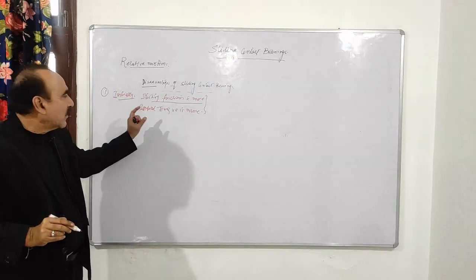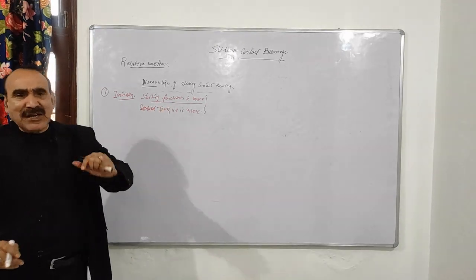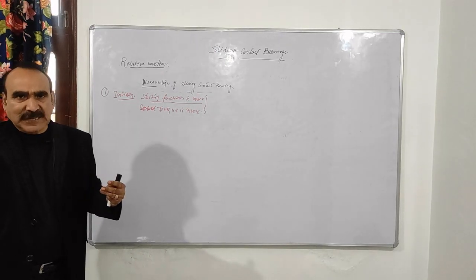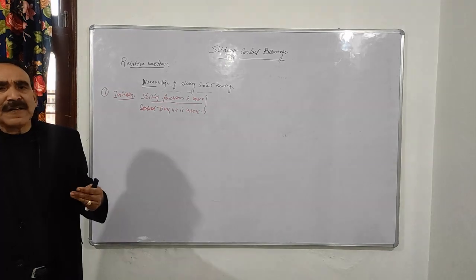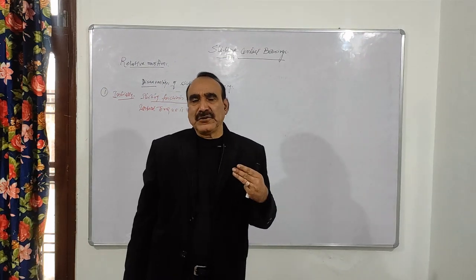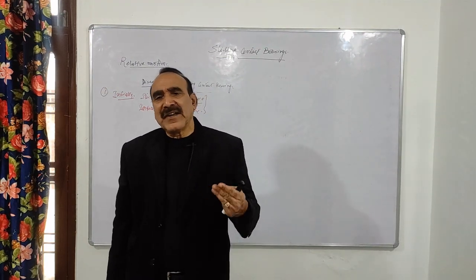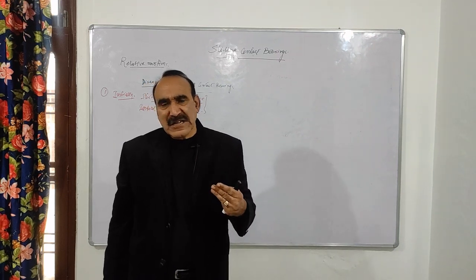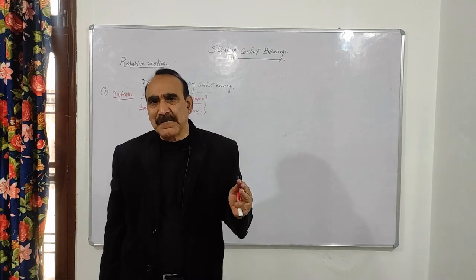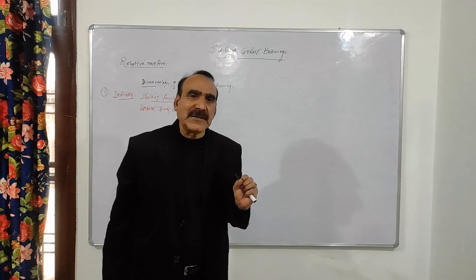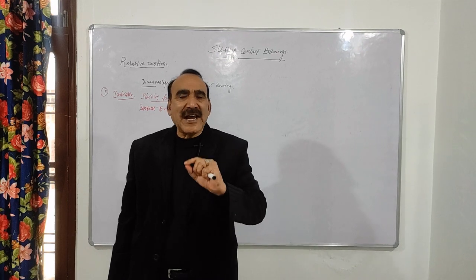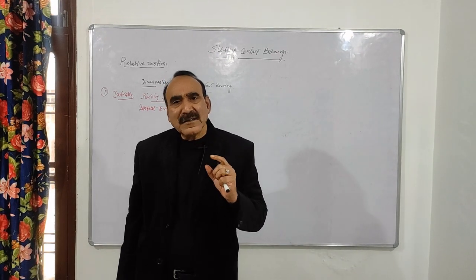इसको दोबारा एक्सप्लेन करेंगे हम कि क्या डिसएडवांटेज है आपका, कि जब हम इंजन को टर्न ऑन करते हैं, राइट, and when it will start rotating, right, when the shaft will start rotating, definitely it will take some time to reach at the maximum operative speed. Suppose this particular bearing is designed at 1000 rpm, right. So it will take some time, first 0, 10, 20, 50, 100, 200, 400, 500, like this. So maybe that time is very short, but it will take some time or few seconds to reach at this operative or running condition.